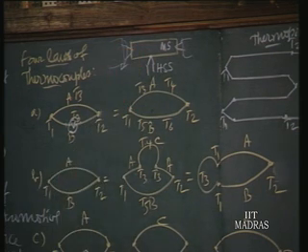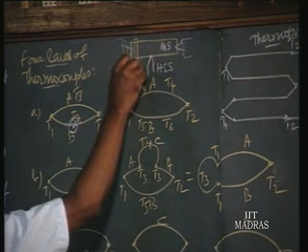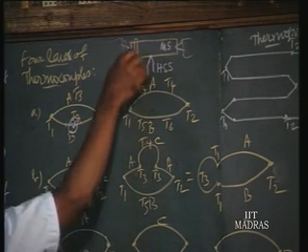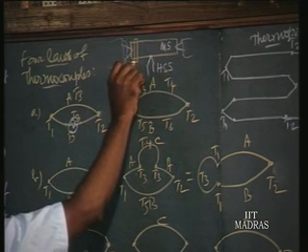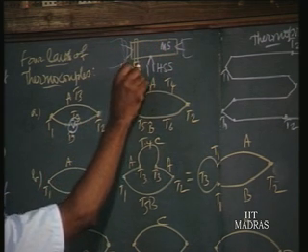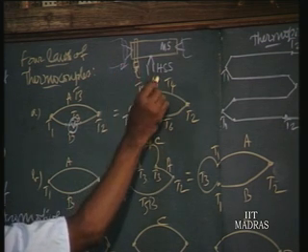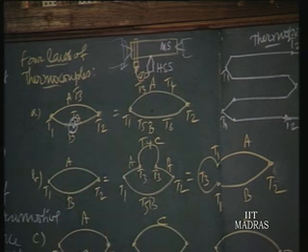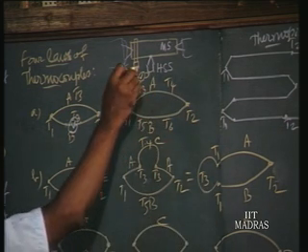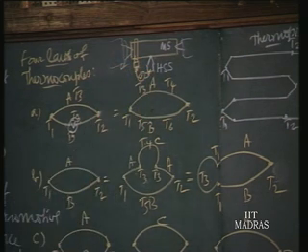Then away from the cutting point, we take another slip ring. Somewhat like slip ring arrangement, and we have the brush contact, with a spring loading, and from this also we take one point. Between these two we connect a voltmeter, and this is analogous to this one. This T1 is the temperature, that is, this is at atmospheric temperature, this is also atmospheric temperature away from the cutting tool.